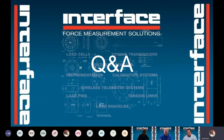And he's got another specific question. In which cases do you have a 72 figures compensation matrix only on a 6-axis sensor with a double bridge? Is that true? That is true, but it's not truly a double bridge. It's 12 bridges, and you're basically running a more complicated matrix calculation. It's basically an extra bridge per bridge to help error correction of the crosstalk.